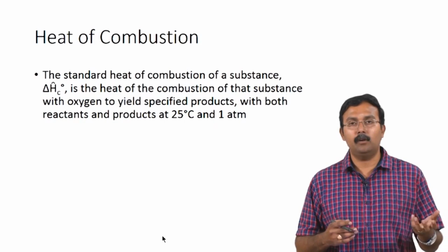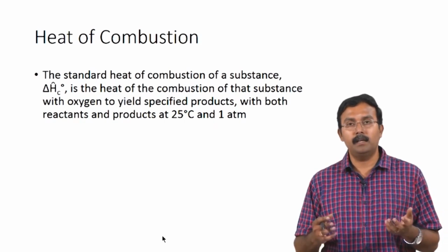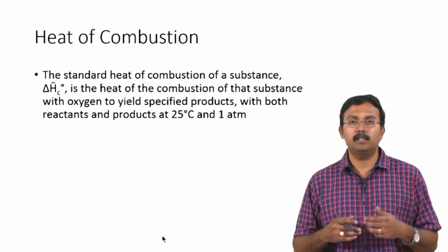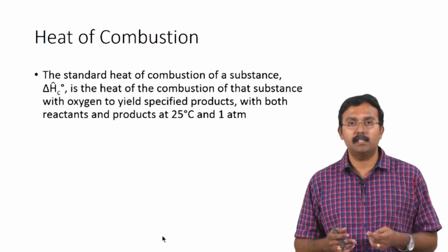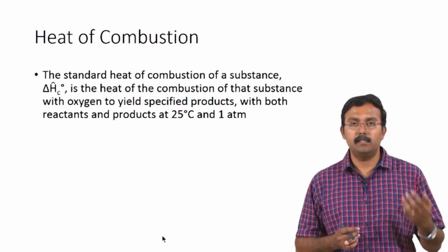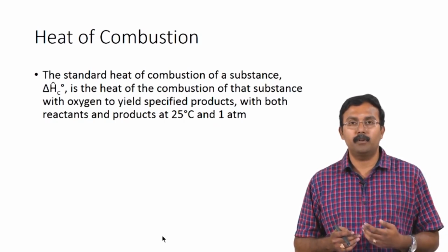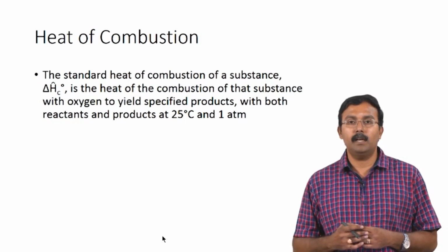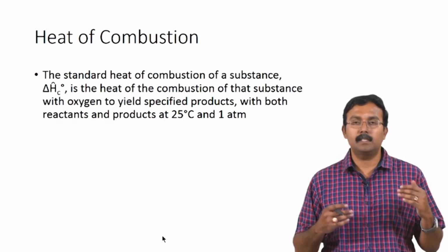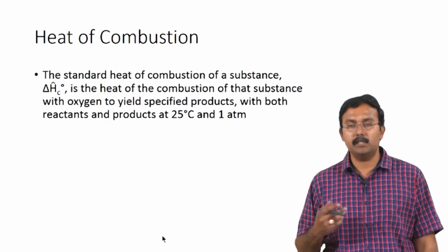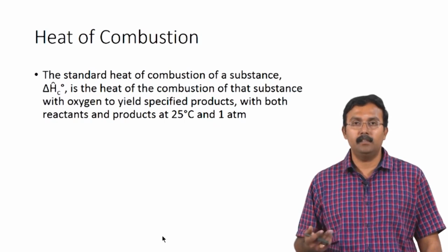So, basically any component which you have, when it is burnt, will produce the combustion products. We have already looked at what is combustion and what complete combustion stands for when we discussed combustion reactions as part of material balances. Please go and look it up and refer back to understand what it is. And when it yields these specific products, assuming the products and the reactants are at the same temperature, the change in enthalpy for this reaction is called the standard heat of combustion.